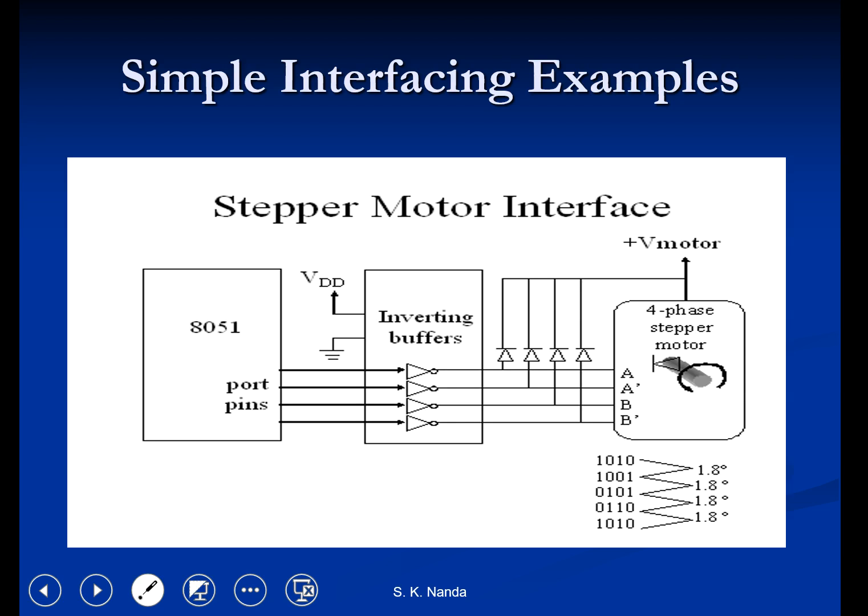Each step in rotation is a fraction of full cycle. This depends on mechanical parts and the driving method also. Similar to all the motors, stepper motors will have stator and rotor. Rotor has permanent magnet and stator has a coil. The basic stepper motor has 4 coils with 90 degrees rotation step, which we have seen in the diagram in previous lectures. These 4 coils are activated in cyclic order. The figure shows you the direction of rotation of shaft also, shown with the arrow.